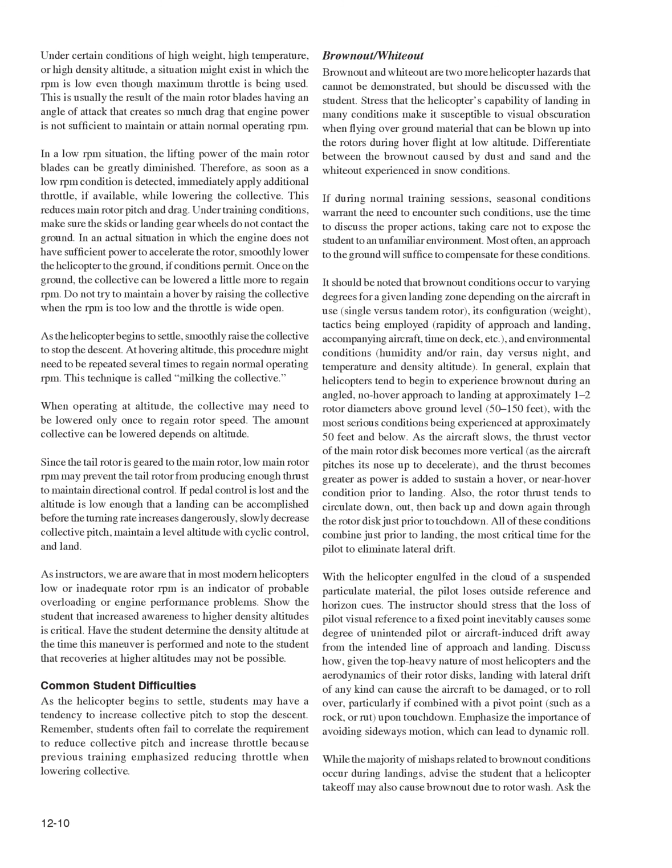It should be noted that brownout conditions occur to varying degrees for a given landing zone depending on the aircraft in use, single versus tandem rotor, its configuration, weight, tactics being employed, rapidity of approach and landing, accompanying aircraft, time on deck, etc., and environmental conditions, humidity and/or rain, day versus night, and temperature and density altitude. In general, explain that helicopters tend to begin to experience brownout during an angled, no-hover approach to landing at approximately 1 to 2 rotor diameters above ground level, 50 to 150 feet, with the most serious conditions being experienced at approximately 50 feet and below.